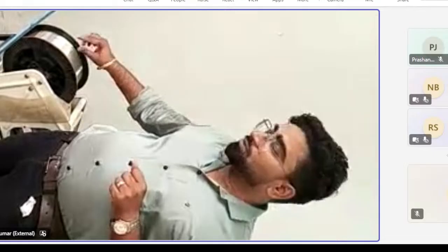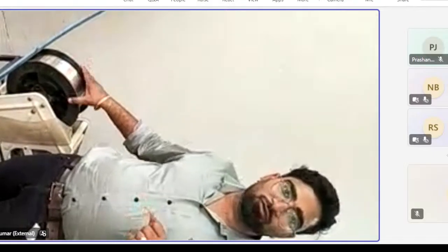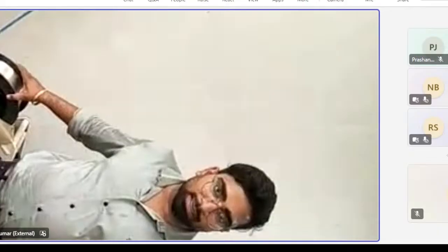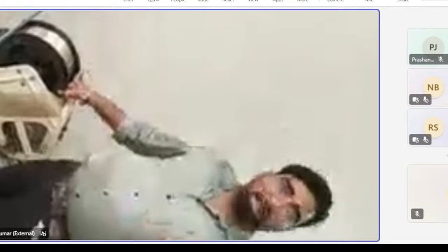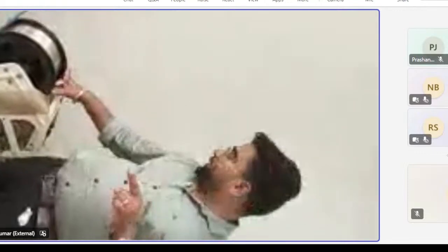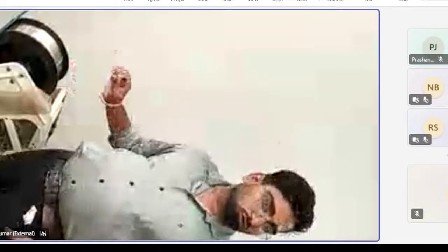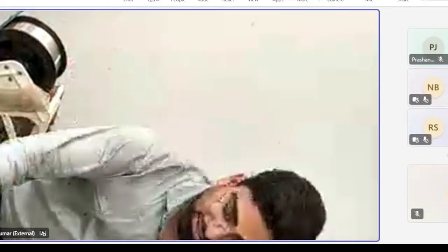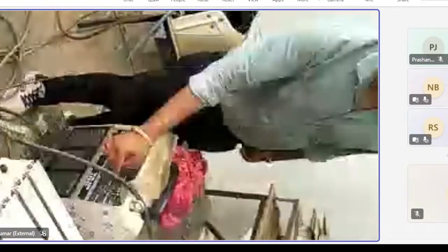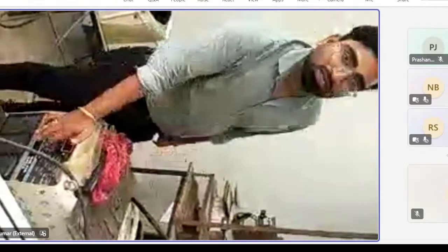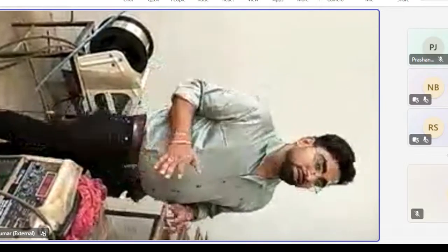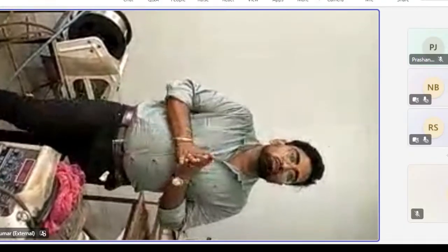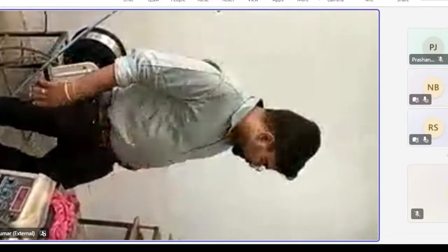The wire diameter we are using here, for this material specifically for the experimental purpose, is ER308L, in which the wire diameter is 0.8. For the wire diameter of 0.8, we have taken a roller of 0.8 diameter. Here we have changed the diameter to 0.8. After that, we have set the GMAW part and the solid part, which are very basic considerations. Otherwise, the experiment will fail and you will not get the appropriate results you desire. So these are the basic setup.